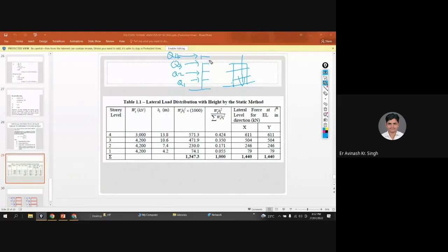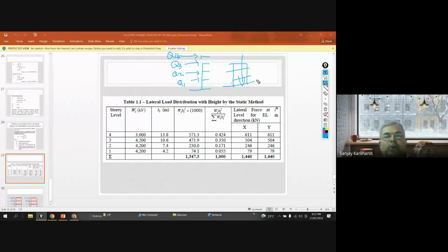The system is the same. For gravity analysis, you applied gravity forces. Now, using the equivalent static load method, you have the lateral forces that might be generated and the floor might be required to resist, and these are maximum. So you are not worried about any force less than this, because if the terrace floor is capable of resisting Q4, it will definitely resist a force less than Q4.